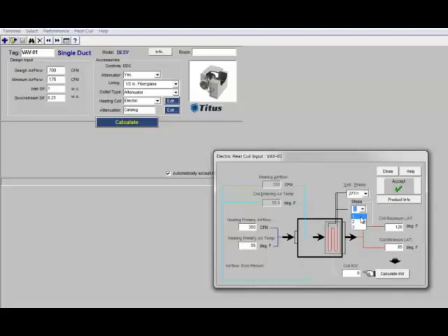Now for small heaters, you typically can get good control with only 1 stage. 3 stages are really not used very often these days. That was more popular when pneumatic controls were being used, when you had to break the heat capacity into more steps to get accurate temperature control. With digital controls or analog electronic controls, it's possible to get very accurate control with a fewer number of stages. These days it's pretty rare to see more than 2-stage heaters being used.